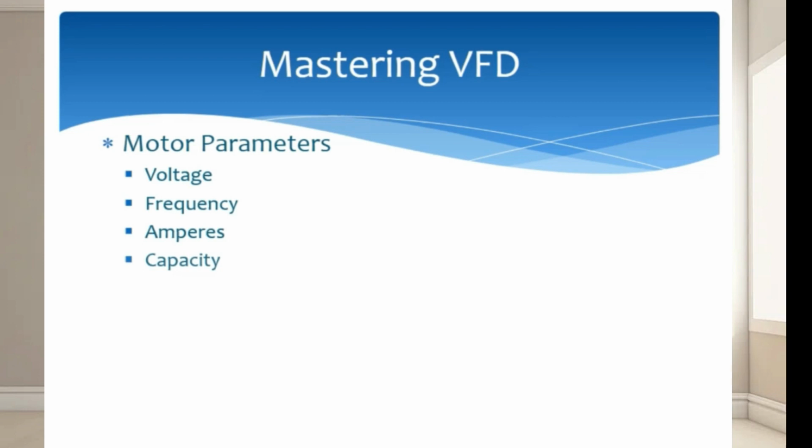So these parameters are efficiency, rated slip, and motor poles. You can see on the screen the formula for rated slip. But before we discuss that, we need some understanding of the term slip. So what is meant by rated slip? Well, in easy words, the speed difference between flux and rotor.